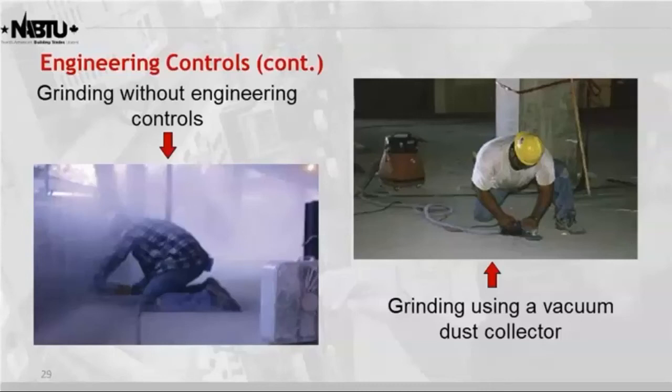If they do not, of course, the safeguards for dust exposure will be hindered. In some cases I've seen workers attach a Y to the same vacuum system and have two workers doing two operations on that same vacuum, and you'll see the dust start to escape, because the dust that's generated is overwhelming the capacity of that vacuum.